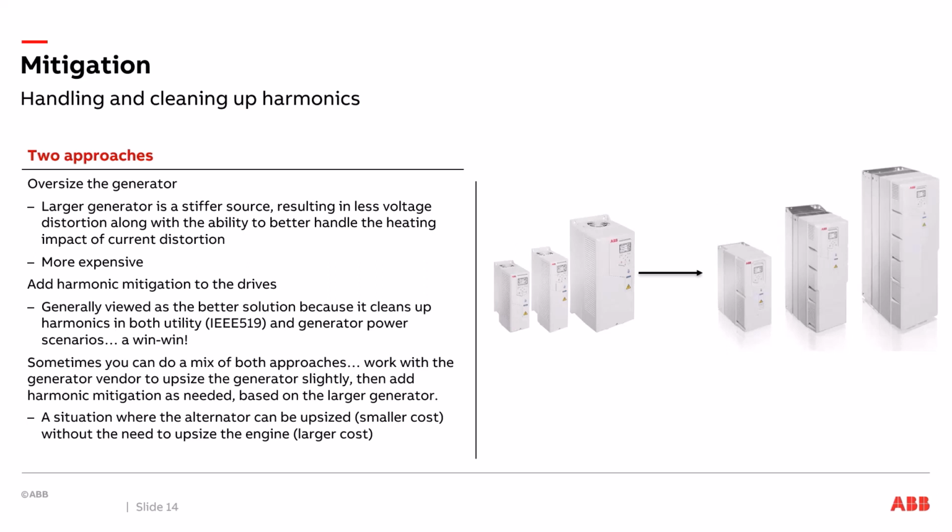So usually this is viewed as the better solution because it cleans up the harmonics both in your normal utility mode, so it makes IEEE 519 happy, but it cleans up the harmonics for your generator power scenario too. So it's really a win-win situation.